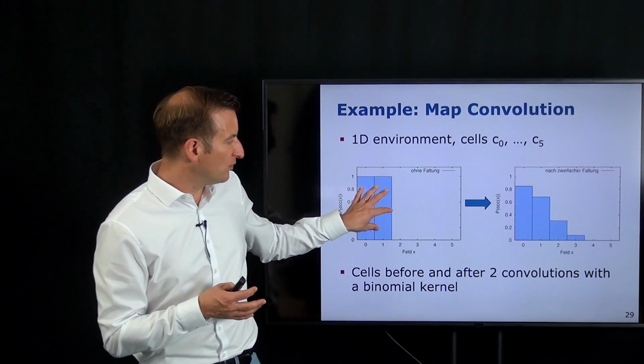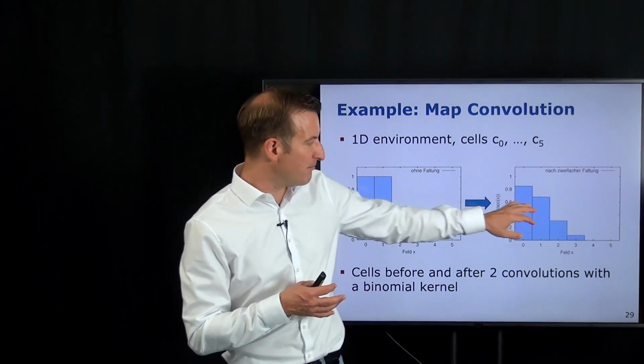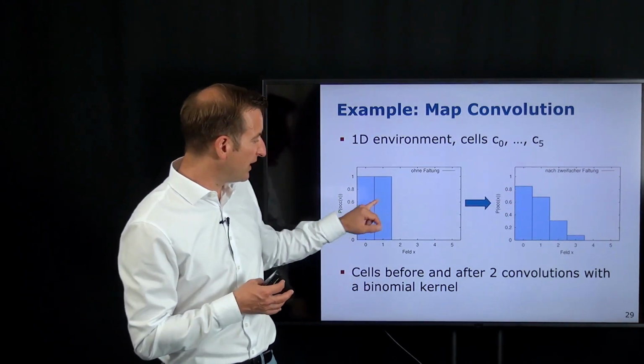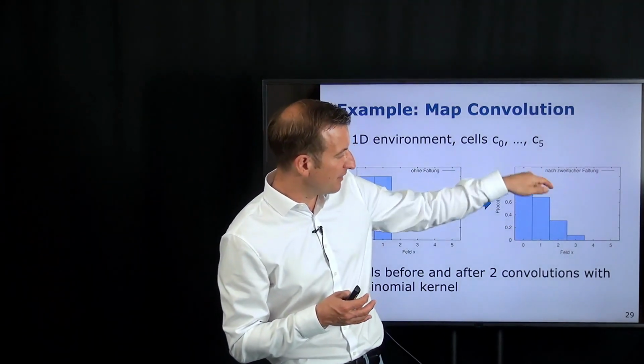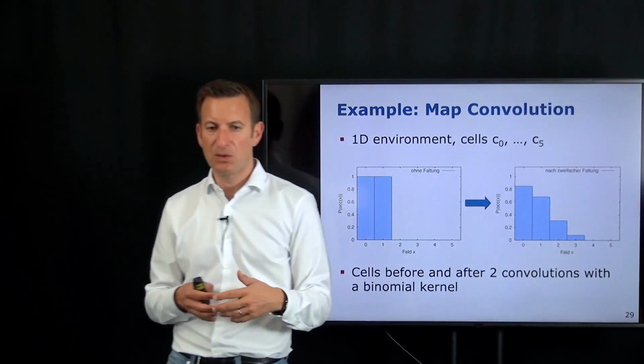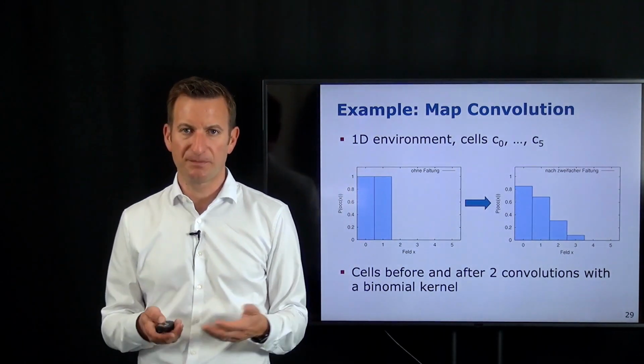What you would probably do is take both of those maps and then take the maximum of those costs. You still want the occupied space to be really forbidden because we know there's an obstacle, but the other cells are still cells the system should avoid.